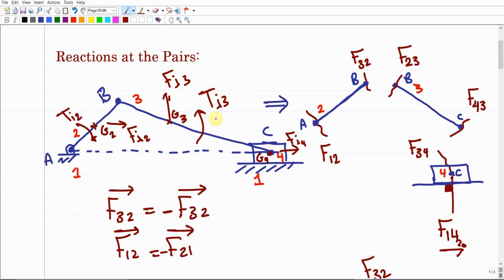And probably for some reason we may have some external force, F external. So in total, we have 2 or even more forces acting in the middle of a link, plus some moment. Your objective is just to combine them as we explained before for the general member case, in the previous video. So the third step is just to combine any forces or moments acting on any specific link into just one force.